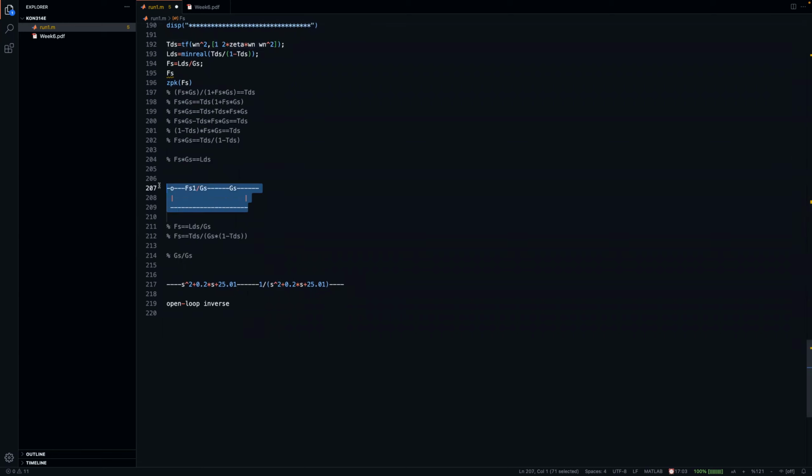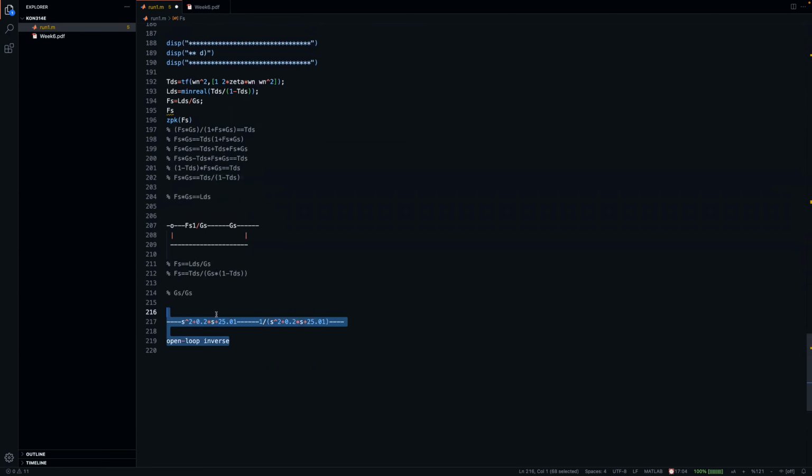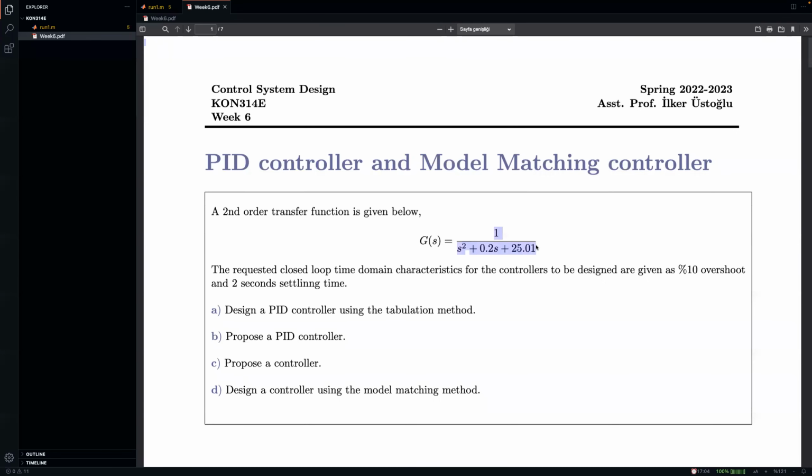But you can see this is something like control with the inverse, but in closed loop. And it relies on the model of the system, as it was the case for control with the inverse here. So we know this as pole zero cancellation, but in this case, for our today's discussion, it seems to be the exact same here, but that's not going to be always the case, because here we had no choice but to get rid of the whole system dynamics, which is just the high frequency part of the system, and there's no other choice.